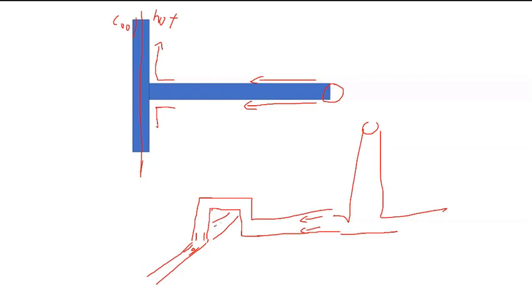But if we check the other side, you can see the same behavior because we change the direction of the melt. Because this one goes from the top to down, and it splits into two directions, so we get a similar temperature distribution on both sides. If we don't use this kind of design, and don't make the melt go up and down, then it will simply have two different temperature distributions.